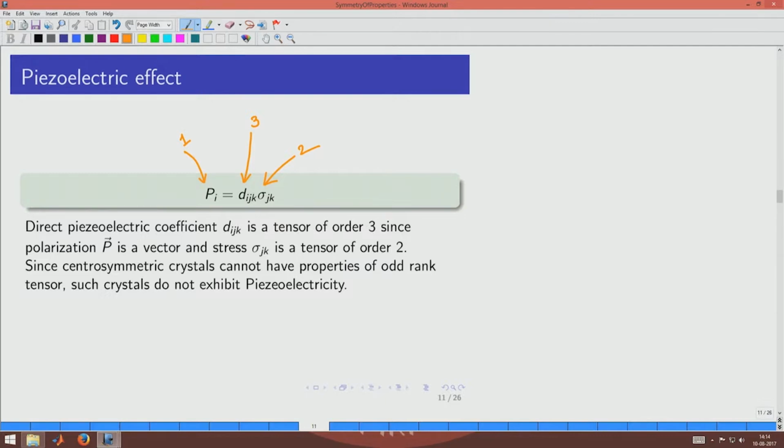And we can see that now we are getting a property that is actually odd number ranked. Okay. So, there is a theorem which shows that if you want a material to possess a property of odd rank, then centrosymmetric crystals will not be able to show it, non-centrosymmetric crystals can show it, and this is something that we can discuss a little later on. But at this moment we mention that the nature of the tensor already is helping us, because certain symmetries of crystals cannot have certain properties, and that is very valuable, because this is a conclusion coming from the order of tensor, and that is coming from the mathematics rather than from experimental measurements.